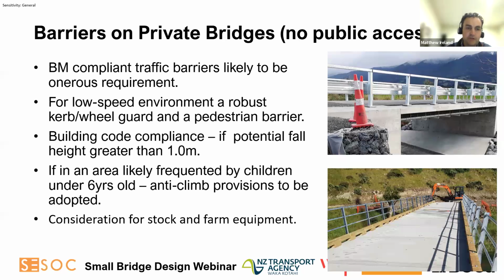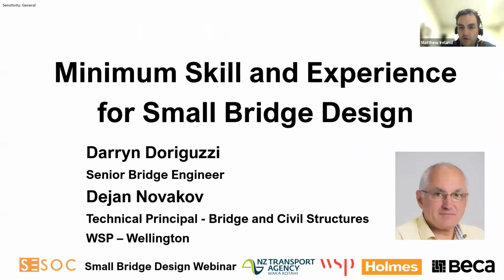And again, as we touched on earlier, if you're designing these bridges in a rural type setting, quite often the local farmer using the bridge will have their thoughts on what's appropriate for their stock, and also some of the farm equipment gets quite large as well. So you need to consider that to make sure that it can actually fit across the bridge. That's just a bit of an overview from me, and I'm going to hand you on to Dayan.